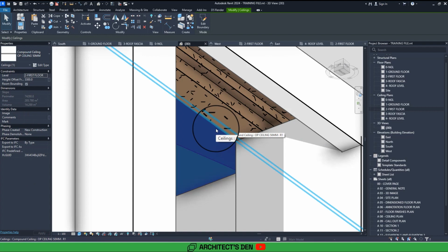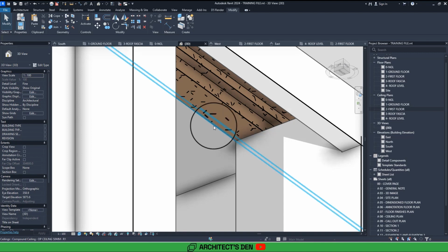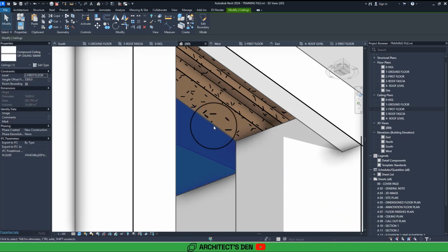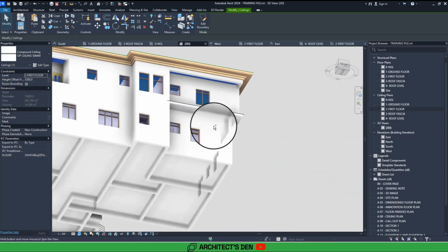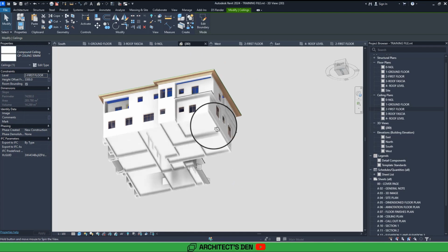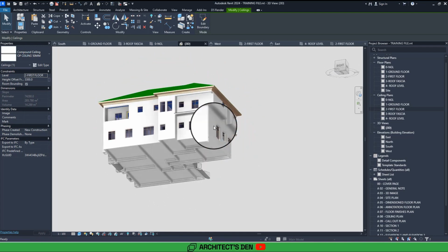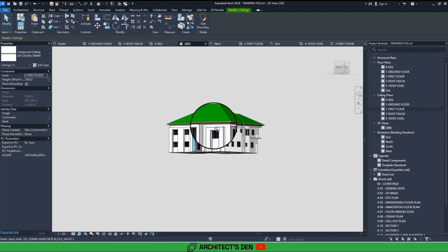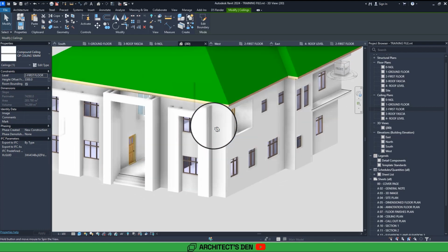So if I select the ceiling, now is something important to note. See, I'm trying to click on this ceiling right here. It's not clicking. You need to go to the edge of the ceiling and you need to allow it to show. So it's at 3.3. That's the offset of the ceiling. So I've created the ceiling, and you can see it's selected, so you can see it in light blue all over the first floor. I can still do that if I wanted in the ground floor also, in areas where I need it to be.